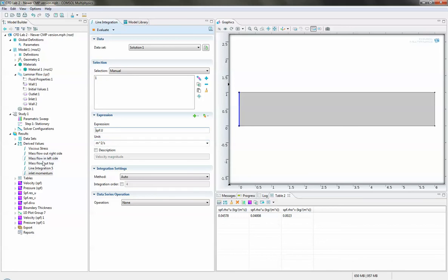So if you go over and just look again at mass flow, you've got to make sure that you get the right density into this momentum equation. So it's this times u times u. Okay, and it will fix the units automatically.